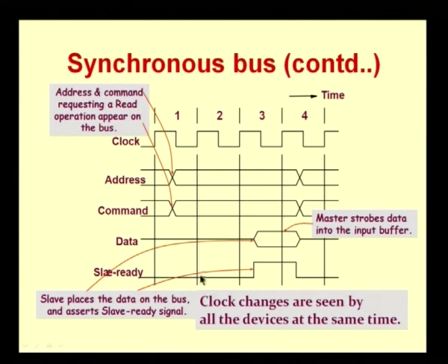By going in for these additional control signals, you can accommodate both faster and slower devices and not compromise on the timing. And if a device is not ready, it would not have put up this slave ready signal, so you will also know that it has not responded. Both these problems can be solved with the help of this kind of additional signal.